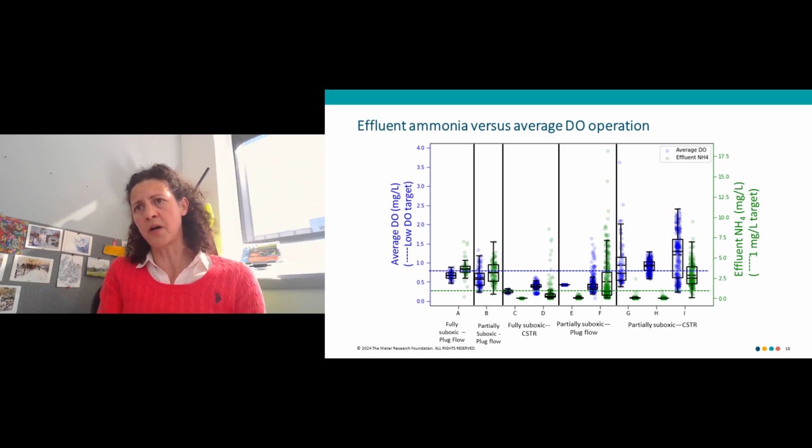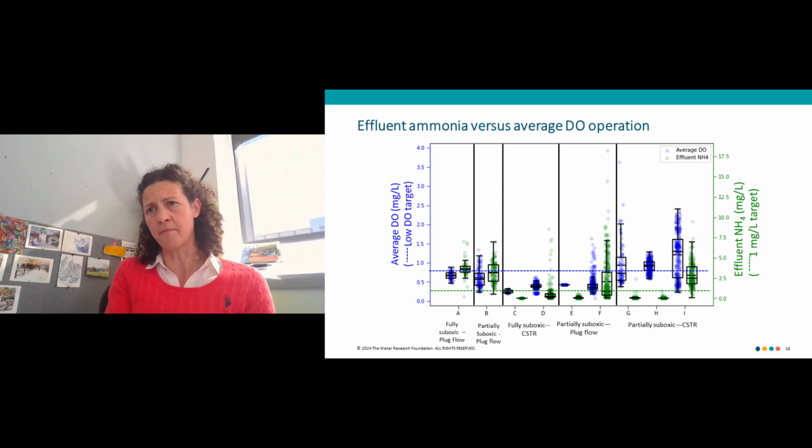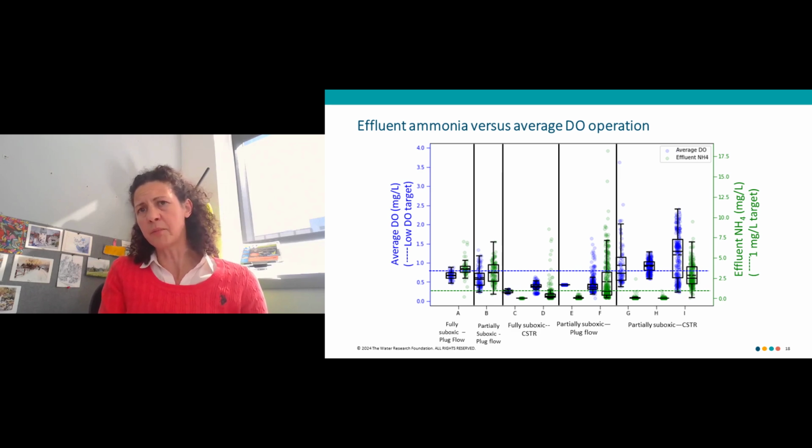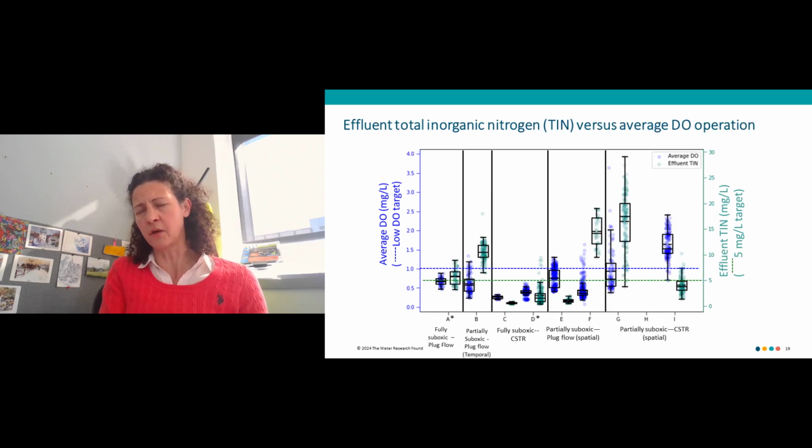And so we'll talk about that more when we talk about the microbiology and the experience we have at Pomona and other facilities, that there is actually a biological mechanism that makes it simpler and more robust to nitrify at low DO condition, even though that sounds first counterintuitive from traditional activated sludge treatment as we learned it traditionally.